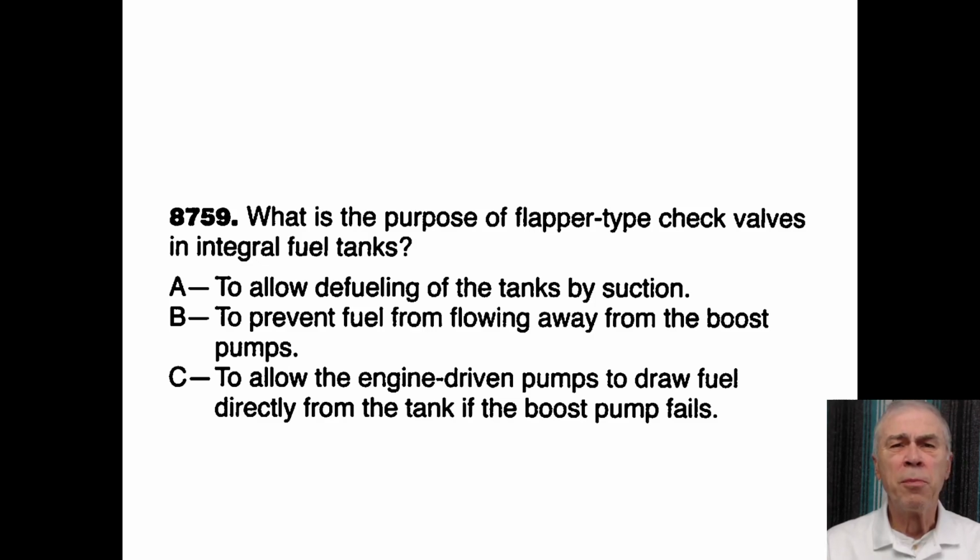And what is the purpose of flapper type check valves in integral fuel tanks? Was it A, to allow defueling by suction? B, to prevent fuel from flowing away from the boost pumps? That's part of it. Or C, to allow the engine-driven pumps to draw fuel directly from the tank if the boost pump fails?